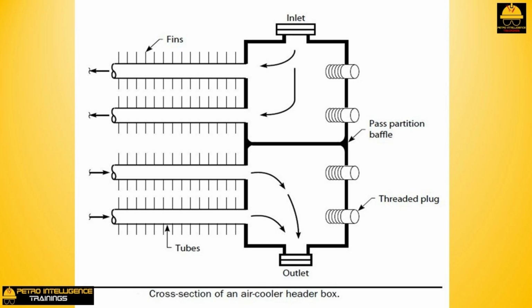A large industrial air cooler may have 2,000 tubes or 4,000 plugs. The labor involved to remove and reinstall all these plugs is formidable. Leaking plugs due to cross-threading is a common startup problem. Hence, many air coolers are simply never cleaned.